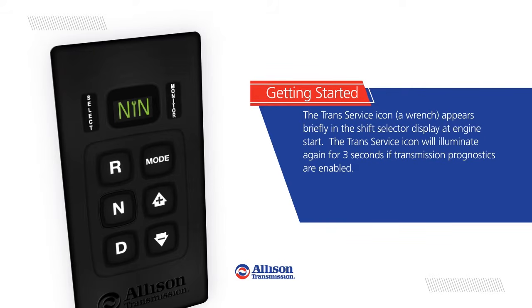The trans service icon, a wrench, appears briefly in the shift selector display at engine start. The trans service icon will illuminate again for 3 seconds if transmission prognostics are enabled.